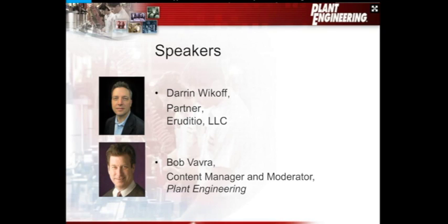Then we look at each one of those spare parts, and if that part is not on the shelf, what is the impact to production, customers, the process, what have you. We also need to look at the other side of the spectrum, and if we do stock it as a risk mitigation control, what is the cost of owning that asset in inventory? So in order to answer the question, one, I've got to see it be high up on the scale in the spares lead time category.